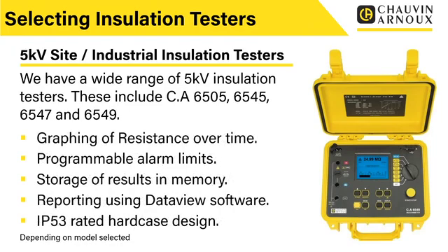Now, a few things we've got also available. Again, these generally tend to be on the higher end, the 6549 products, but you've got the ability to graph the resistance over time. With some of the products, that's via the software, but on the 6549, it will actually plot on the screen a graph of insulation resistance over time for you, which is really useful when you're carrying out the test, particularly if you're in the field. You don't have to download those results to a laptop and have a look at that. You can physically see that curve on the screen of the tester while you're carrying out the test.